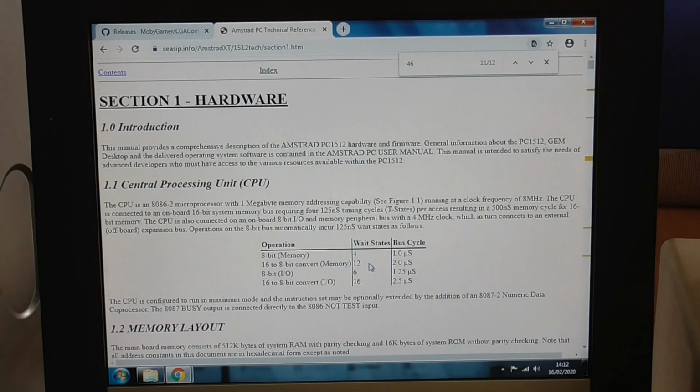And then I decided to try and figure out how many no-ops I could insert between these writes. So some of the writes I could fit more no-ops between because there were more wait states in that gap, and others I would have fewer no-ops. And I finally realized that the longest of those gaps is surely the horizontal retrace period, that 46 cycle one. Now actually I could only find a combination that would allow me to fit 5 no-ops between 2 word writes, and that only equates to about 20 cycles.